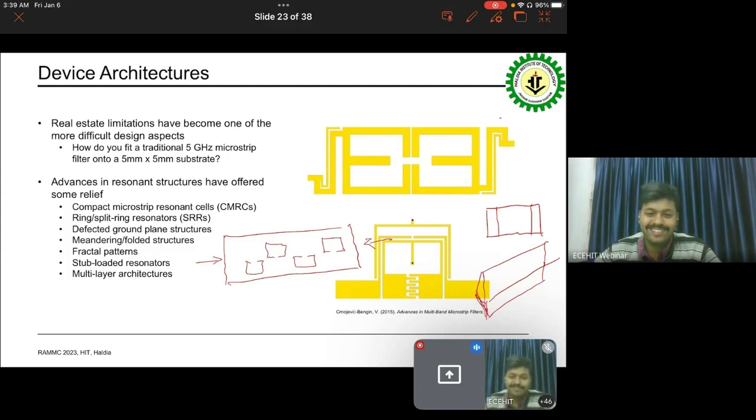Okay. So if you're looking at this lengthwise in the waveguide, you'll usually have some form of rectangular structure here that's going to change the reactance in that portion of the waveguide. Each one of these forms a different pole on the filter, such that an incident wave is going to be affected by these various irises. Another method is a big inductive post that's stuck all the way through the waveguide. You'll see this as well.